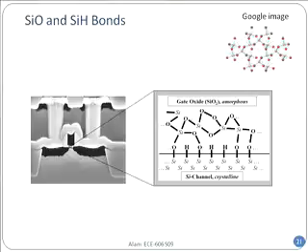Silicon is beautiful. Every atom is where it's supposed to be. But as soon as you go to the oxide, first of all, oxide is amorphous, meaning the atoms are in random places. So that's what I have shown here, that the silicon and oxygen are sort of randomly configured. And then there are also dangling bonds like silicon hydrogen, and I'll explain in a second why they come.